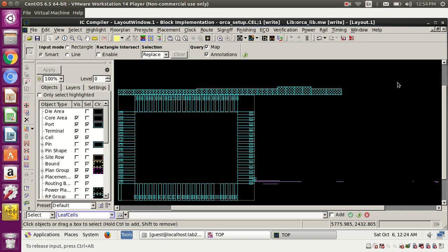That's the reason for vertical and horizontal, because when we have some 10 metal layers, no other way can be more optimistic than vertical and horizontal. If we put M1 as horizontal, then whatever number of tracks we have, we can use all the tracks for M1, and then all those tracks are free for M2 and the other layers also, they can use them too.